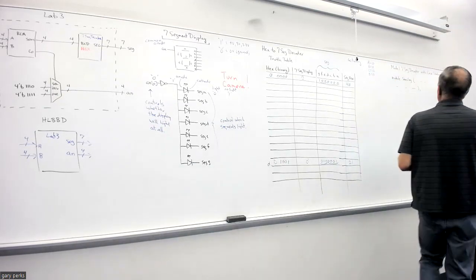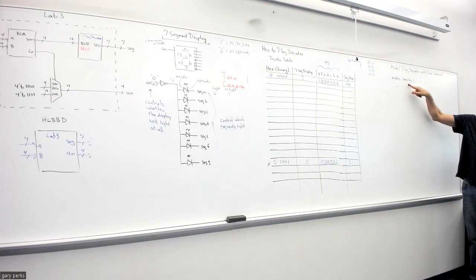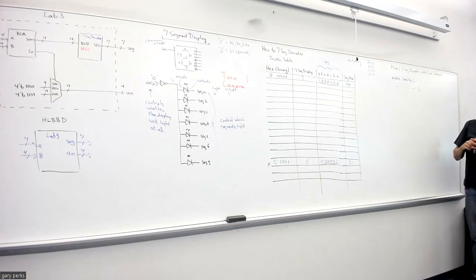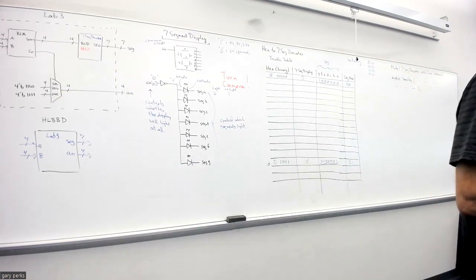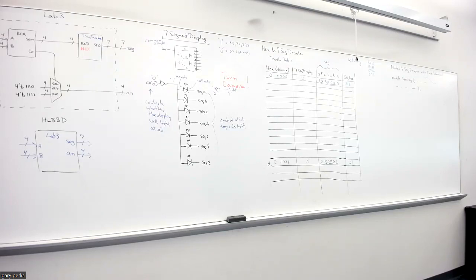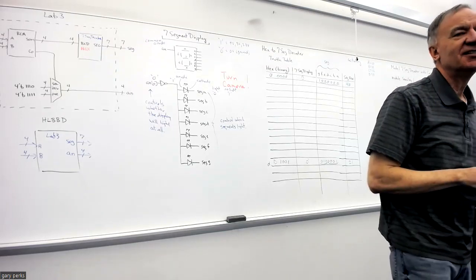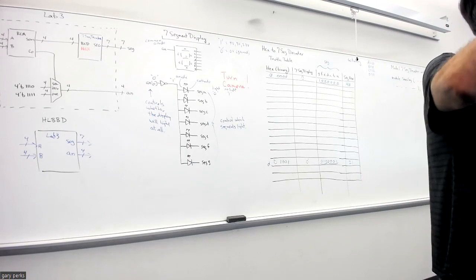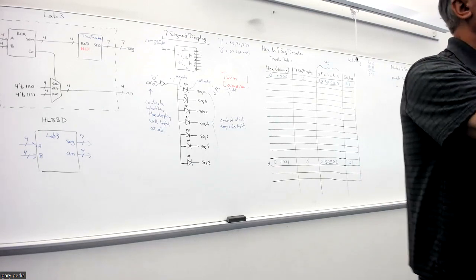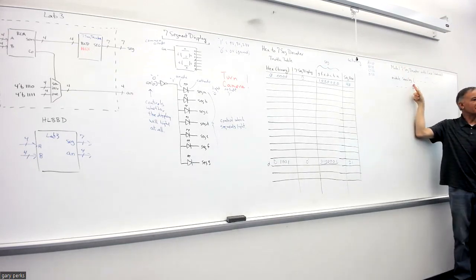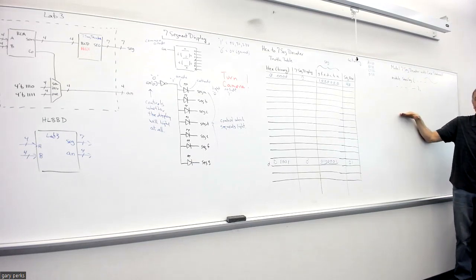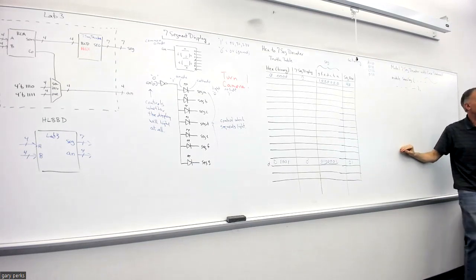Now, just like any module, you start off with the name. So maybe you call this 7seg. Then you have to declare your inputs and outputs. Just like when you did the if statement, and this was something I forgot to mention during the lecture part, but then somebody caught it, I think this table over here caught the thing I omitted. When you declare your outputs, you have to include something when you have an output within an always_comb block.